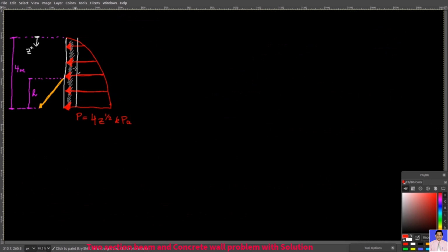I have a wall here. It consists of two plates and wet concrete in between. That's the gray color. This wet concrete exerts pressure distribution along the wall as shown in the image. Here you are seeing it from the side in 2D. In 3D it looks something like this. Note that we assume that the positive Z direction is down.